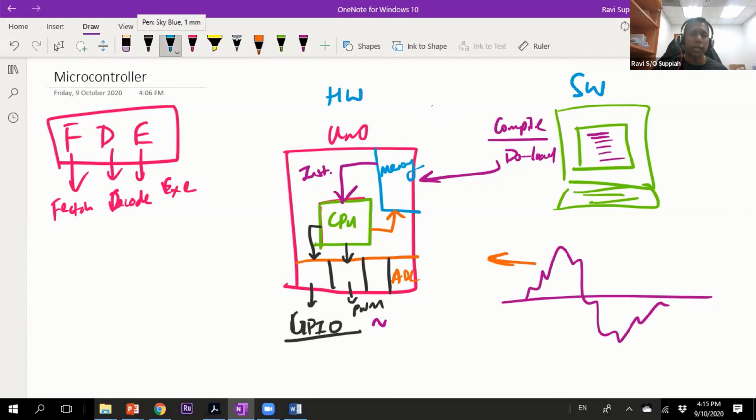And if I want to do that, I can only use specific pins on my Arduino Uno that are written as analog pins. If you look at your Arduino Uno board, you will see that there are some pins dedicated to analog. So only those pins can be used for analog to digital conversion. So there are some restrictions on which pins you can use for some of these specific purposes. Again, this involves some planning ahead when you are building your project.